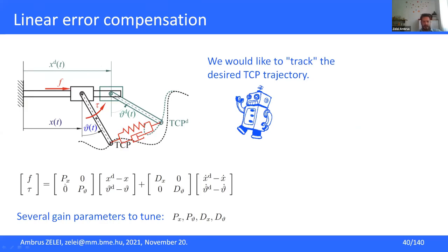And that's why we can call it distributed, because this controller calculates the force, which is up here, and the force deals only with the positioning error in X direction, and the tau deals with the angular error only, and it doesn't have any information on the dynamics of the whole system. And we see that there are a lot of parameters to tune, but this is not the biggest problem.